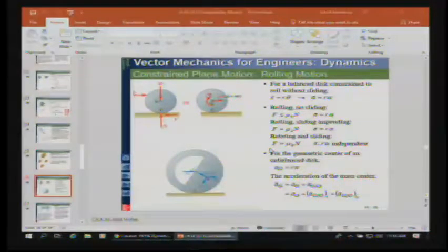Well, there is another advantage not shown in this equation by putting on the gas, which is if you spin, you create friction in the spin itself, and you can generate heat, and you can actually melt a little bit of the surface that you're slipping on. So there's that, and that's actually, well, I'm not going to get into that. There's an application for that, but it's hard for me to draw the connection here. But anyway, the basic thing is that in general, from a strictly static and kinetic point of view of friction, if you need more friction, it's better to stay in the static range almost all of the time.